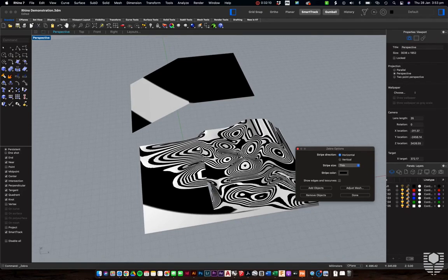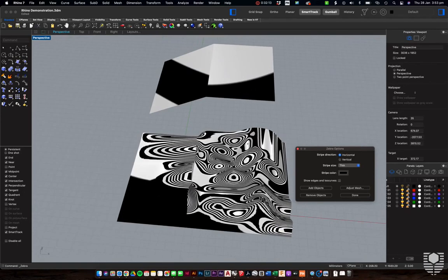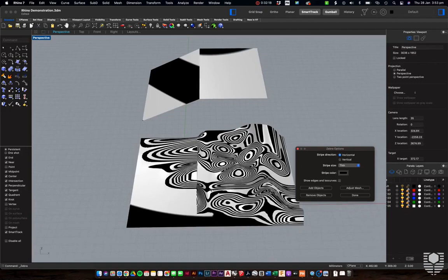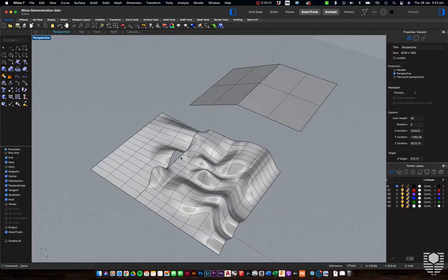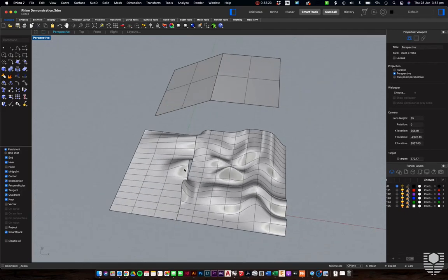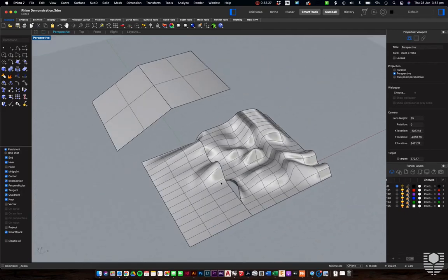And then this one over here as well, these squiggles should line up perfectly. And in some points here, we can see the lines are working to match together, and other points they're completely off. And if we turn this off, we can see why. We've got a peak here with a trough over there, and vice versa on this side. So they're really not matching well as an edge condition. And this is again going to become a problem for us when we're 3D printing later. So we need to make sure we know how to fix this.